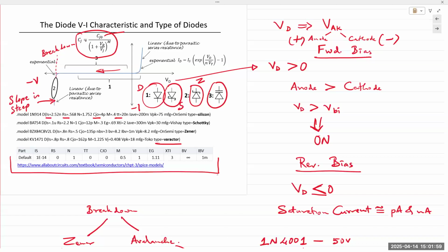The fixed junction capacitance is known as CJO. And CJO, or CJ0, is a function, again, of the geometry and the doping profile of the diode. And then the applied voltage will change the space charge region, will expand or shrink it. And so the capacitance can be changed. And so that's the varactor diode.